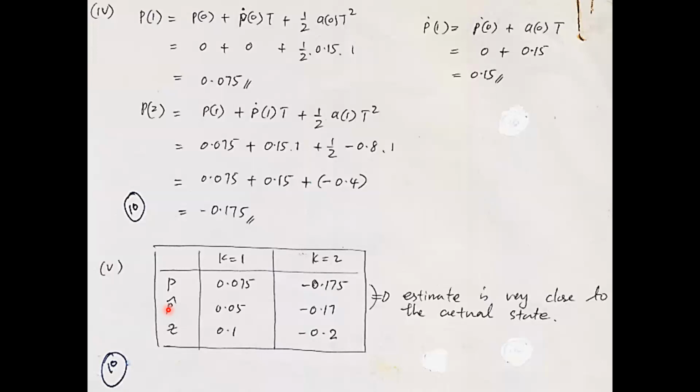This is good because now you can use the state estimate of the Kalman filter as feedback to the control system. If you design a state feedback controller or an LQR controller, you need the state feedback, right? And now the Kalman filter generates all of these state values so that you can use them for feedback.